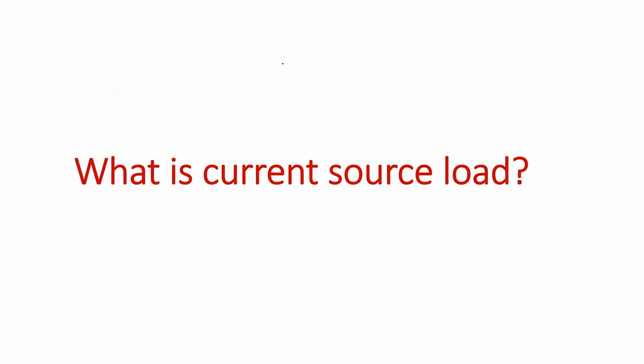Okay. So now the point is, what is the current source actually? Any MOSFET which we are using in saturation, suppose this is your VDD voltage and this gate is biased with some voltage, suppose the source is grounded or connected to some value. When this biasing is set such that this particular device is acting in saturation, then it is nothing but a current source. Because if this device is acting in saturation, for simplicity, if I'm ignoring the CLM, if lambda is 0, means